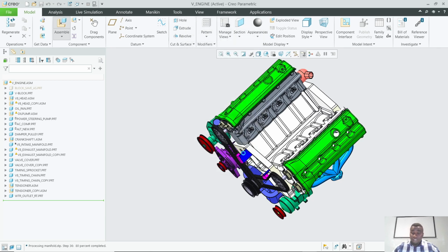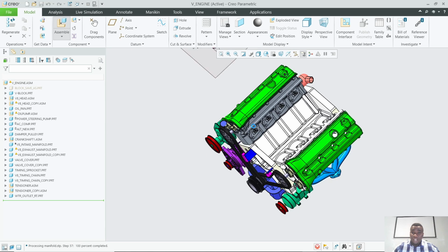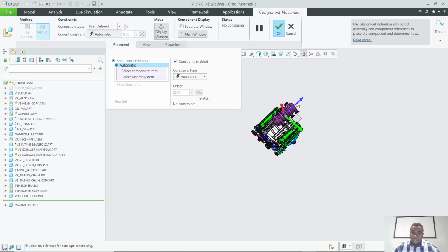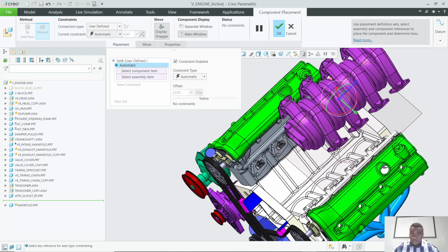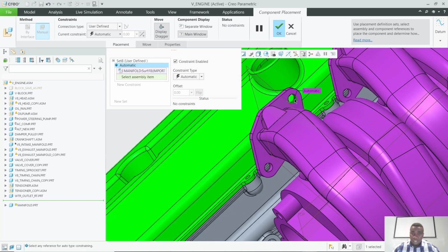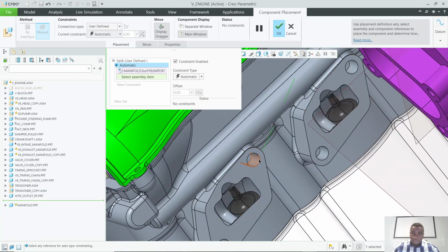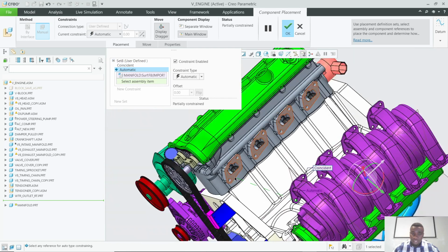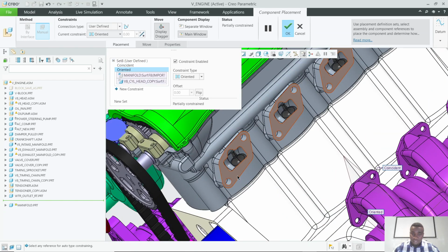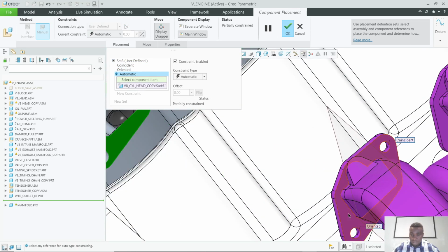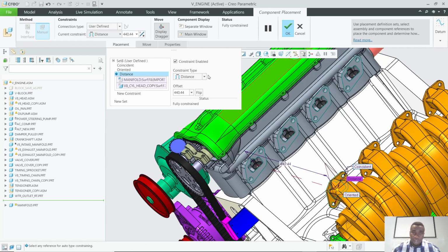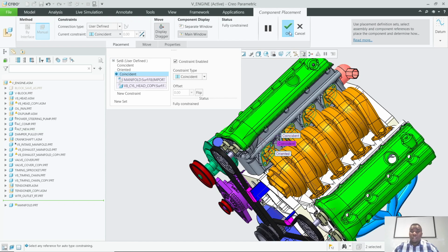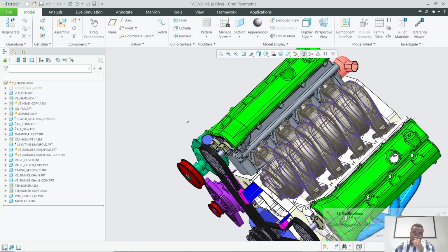What we are interested in doing is that we want to then align it properly. So here it is. We're going to move this part somewhere close by here. We want to align it using that hole there and this hole. We're going to align it using that hole and that one. Lastly, that surface there, query select the back surface there. Then we're going to make it coincident. Okay, and then after that, that is fine.